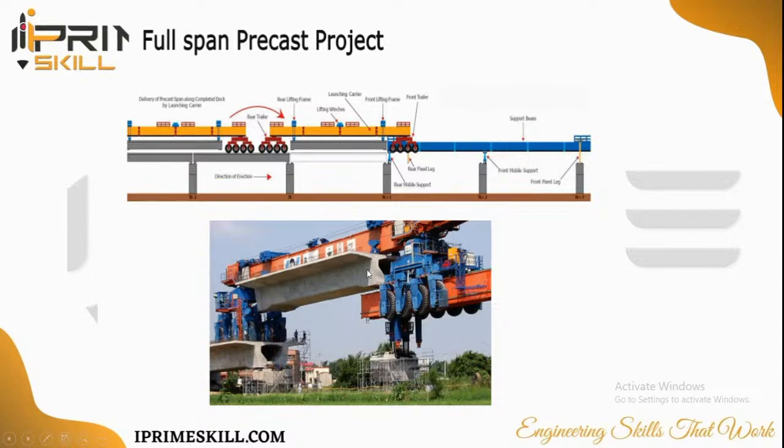See how the girders are brought here by cranes. They're called gantry girders. First the columns are built. Over that, you can see the shape now, the box sections, and they are placed. This is called full span. It sits over the full span. Sometimes half by half. When the span is very small, they will bring each girder and place it, not for the full span. Here you can see that's a full span. This full beam will sit over this pier. That's called full span cast project.